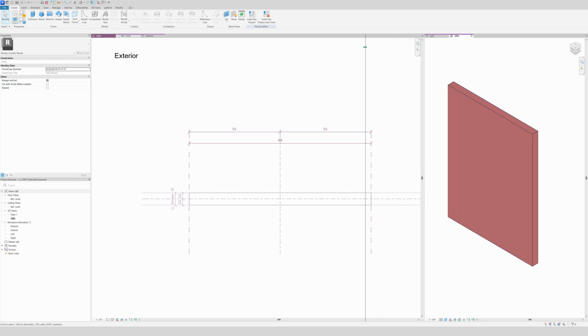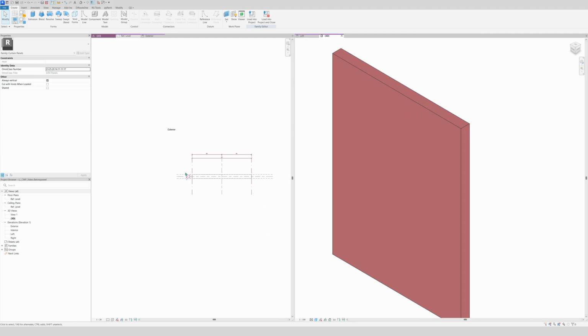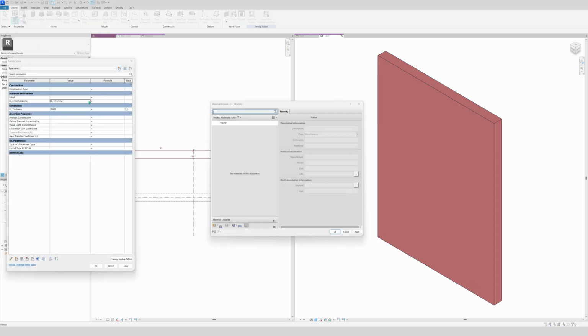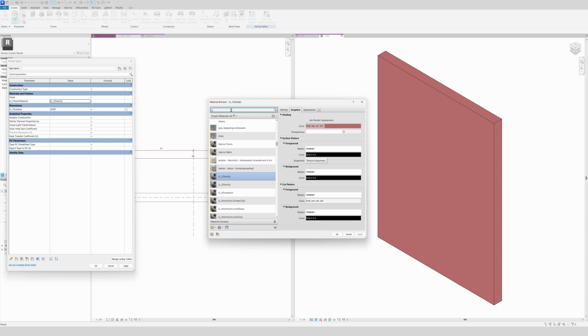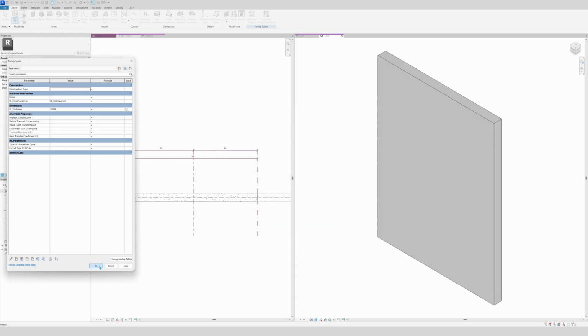So I will slice this bar a little bit like this, so we see our 3D model correctly. And this we're gonna zoom out, you're gonna click on it. Well, shortcut ZA, and voila, you have everything right into the middle. Excuse me. We will set the scale to 120, voila. But first I will change the material, because red is not my favorite thing. I loaded some other materials from my project into the family, so we can have the right material as we wish.